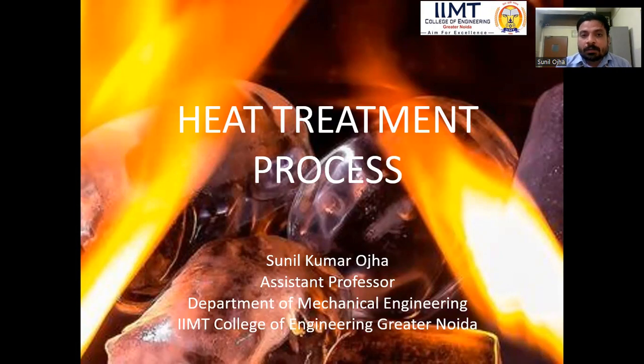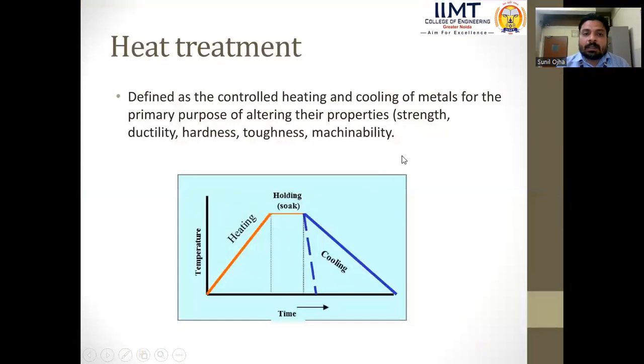So, what is heat treatment? If we want to change the mechanical properties of a material, then as defined, heat treatment is a controlled heating and cooling of metals for the primary purpose of altering their properties like strength, ductility, hardness, toughness, and machinability. On the axes, there is temperature and there is time. We heat the material, hold it for a particular time, and apply a different cooling rate.